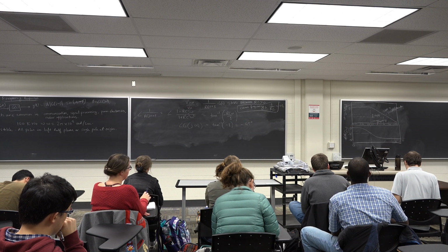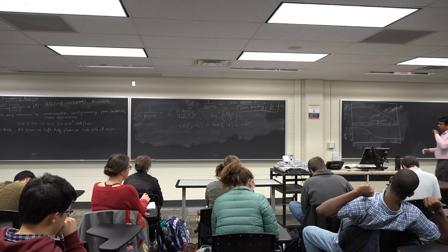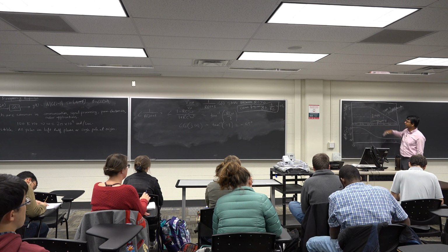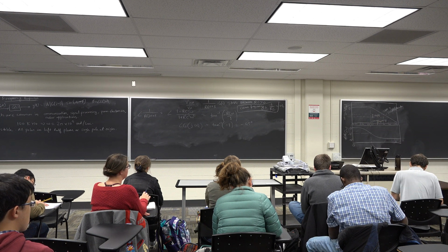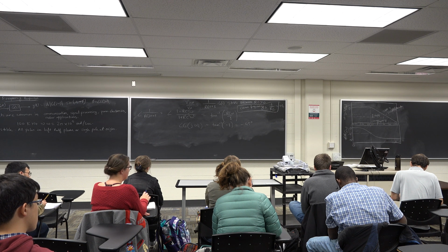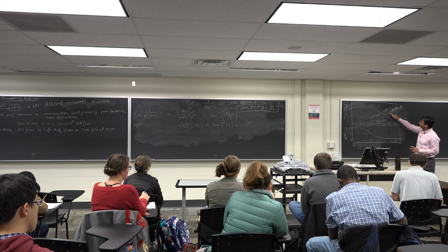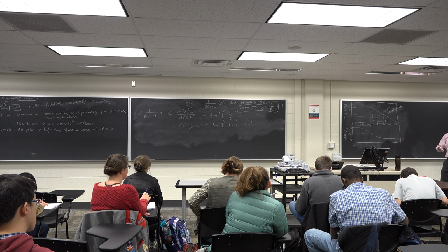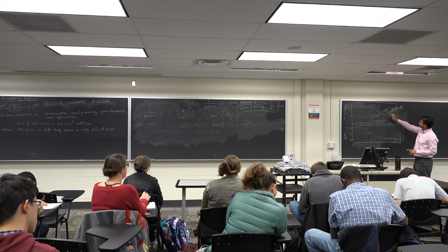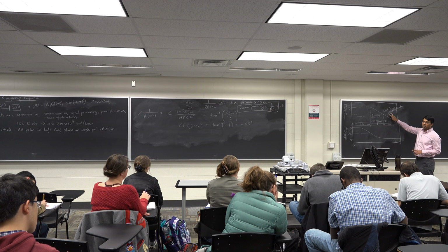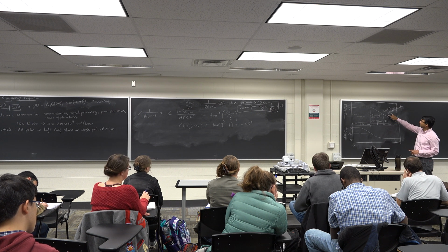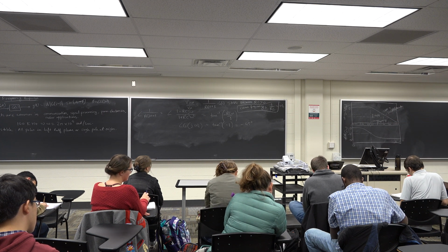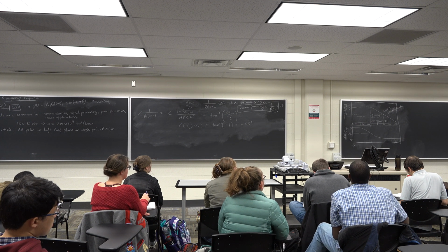And one thing that we will study perhaps in the next class or the class after, the change in the phase angle and the corner frequencies will give you information about whether you have zeros, and how many. The asymptotic slope is going to give you information about the order of the transfer function, whether it's first order, second order, third order, and so on. A first order transfer function will have an asymptotic slope of minus 20 dB per decade, as we have shown. A second order transfer function will have a slope of minus 40 dB per decade. A third order transfer function will have a slope of minus 60 dB per decade, and so on. So it will give you information about the order of the transfer function.